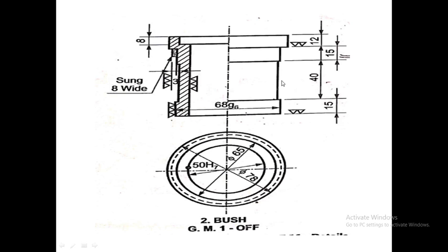Students, we have learned that if a hidden line and a visible line are coinciding with each other, then we always represent the visible line, we never show the hidden line. Similarly here, if one cylindrical hole is overlapping with another cylindrical part and this cylindrical hole is visible whereas this cylindrical part is not visible, even though this part is not visible, we will not draw a dotted line because the circle for this part will be coinciding with the circle for this hole in the top view.